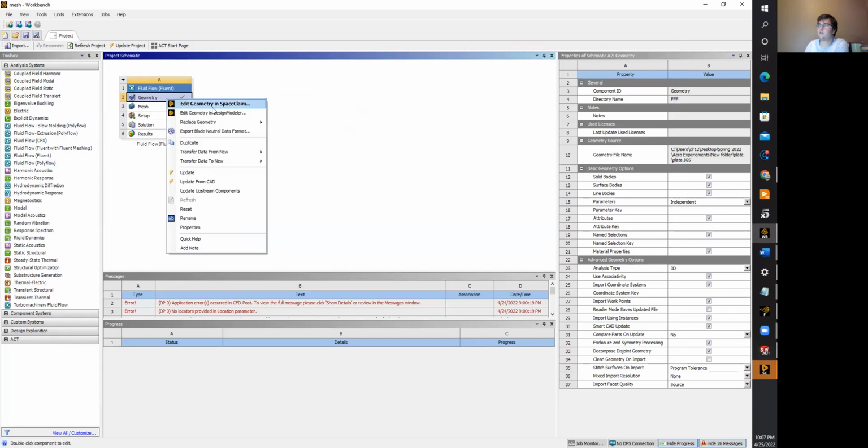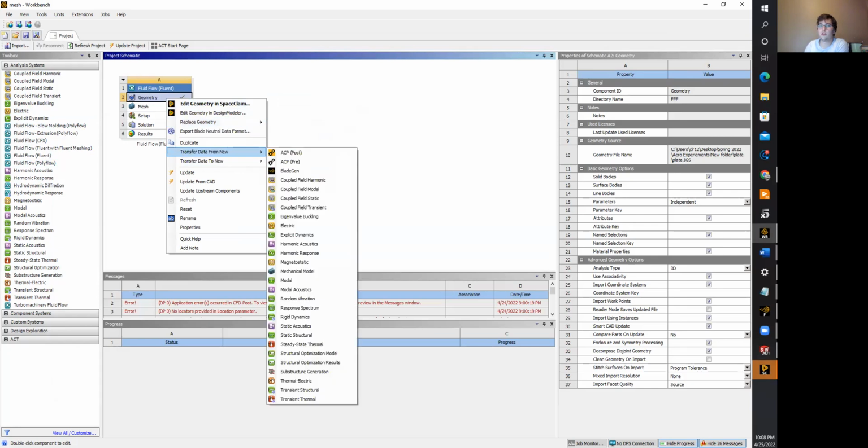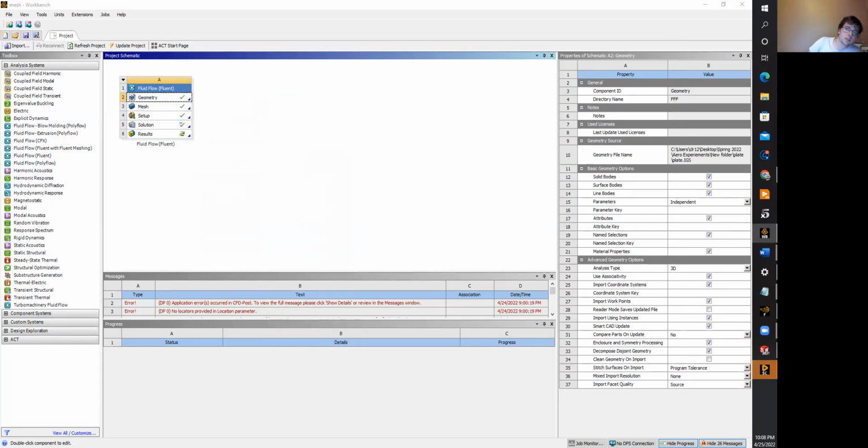So we just go ahead, right click, replace, and then you can browse part one. I have a plate, 15 degrees, all of that. You can see this is my SolidWorks, and this is that IGS one I was talking about. And I can actually go ahead and close that. If you double click on geometry, it'll actually open up a mini SolidWorks. I don't want to say mini, but just I guess a less used.